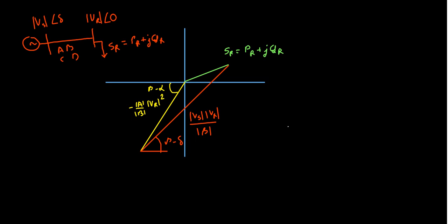Yes, I can change, because this phasor is going to be fixed, minus A upon B VR square, because we have fixed VR. A and B, they are the transmission line ABCD parameters, so they cannot be changed. This angle is beta minus alpha, so beta is also fixed, alpha is also fixed, being the parameter of the transmission line, so that cannot be changed.